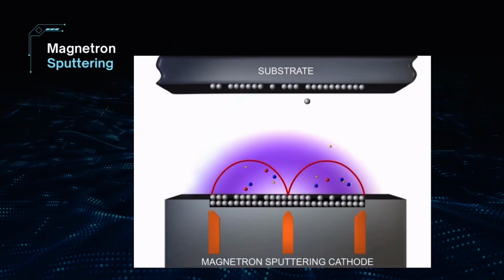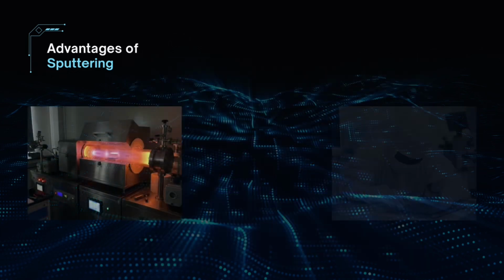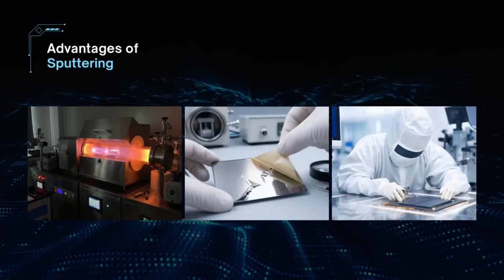Magnetron sputtering uses an additional magnetic field near the target. The magnetic field traps electrons close to the target surface, increasing ionization efficiency. This leads to higher deposition rates and reduced substrate heating. Sputtering offers several advantages, including low deposition temperature, strong film adhesion, high uniformity, and precise control over film composition. These advantages make sputtering suitable for advanced thin film applications.